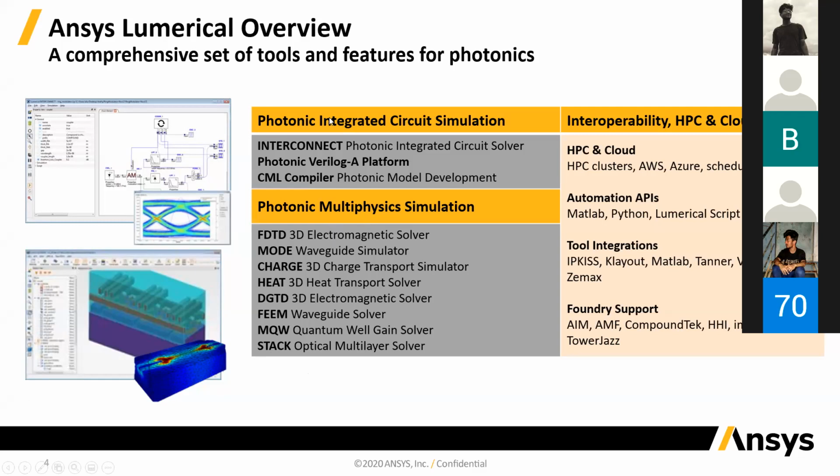On the photonic integrated circuit simulation side, we have INTERCONNECT, which is a circuit solver. Well, I guess in theory, similar to SPICE, but it allows you to simulate your photonic integrated circuit, see how light is flowing from one component to another, and figure out the behavior of a big photonic circuit. We also have a photonic Verilog-A platform. If you're interested in photonic circuit simulations, then this gives you an alternative way to perform those simulations.